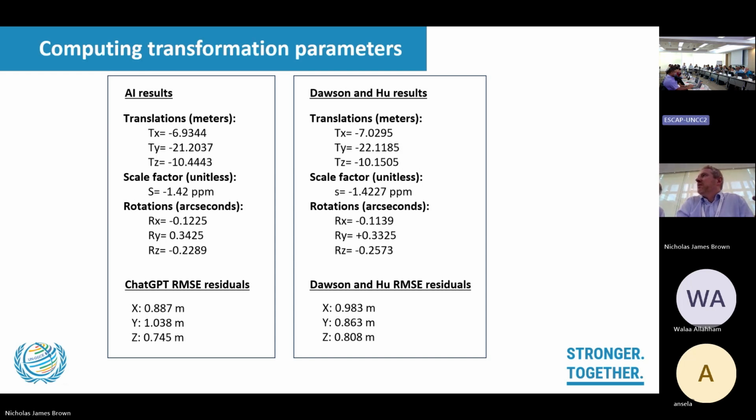You can kind of set the height to 0. We had a little look at the model that underpins the GDA 2020 datum, the plate motion model that's involved there. There's a couple of assumptions with these transformations. The first is that we're looking at rigid body motion; the continent's not deforming when you're deriving the parameters. And the second is that the motion is over the surface of a sphere.